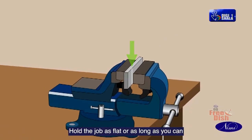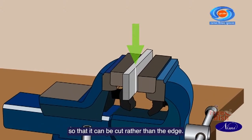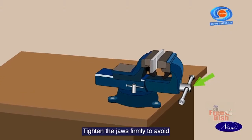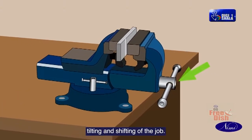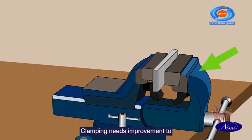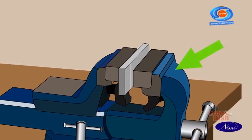Hold the job as flat or as long as you can so that it can be cut rather than the edge. Tighten the jaws firmly to avoid tilting and shifting of the job. Clamping needs improvement to reduce chattering and vibration.